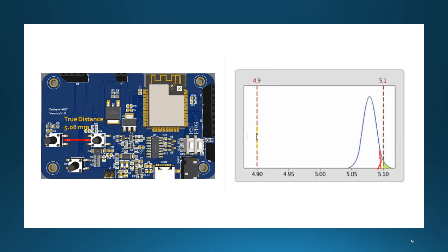So why did this occur? With a percent tolerance of 47.98%, there is a chance that the PCBA viewer measurement tool will measure an in-spec board as out of spec.